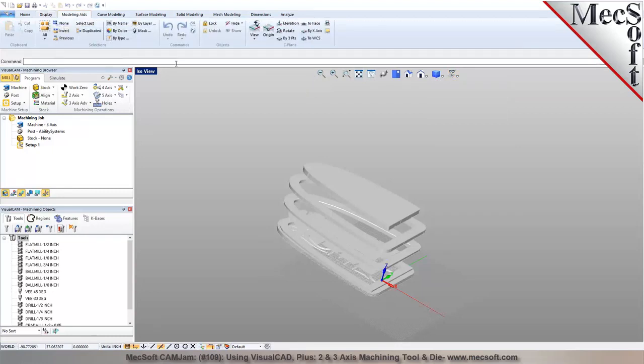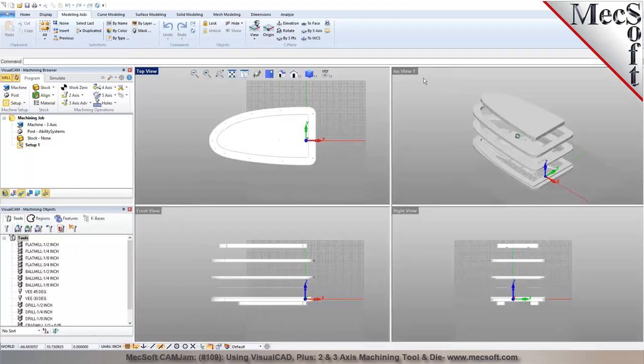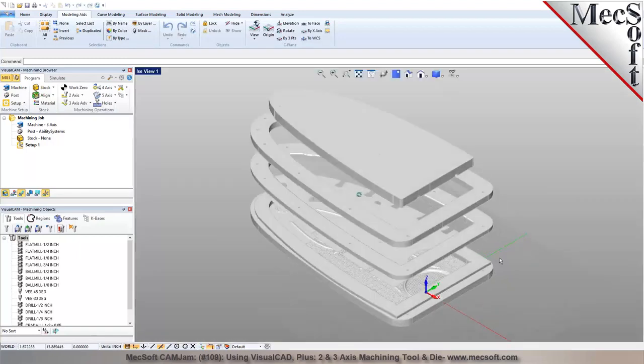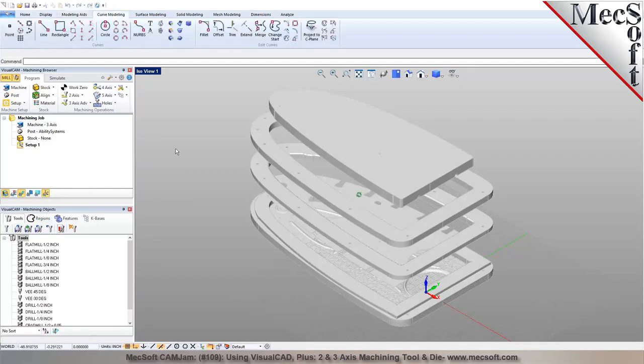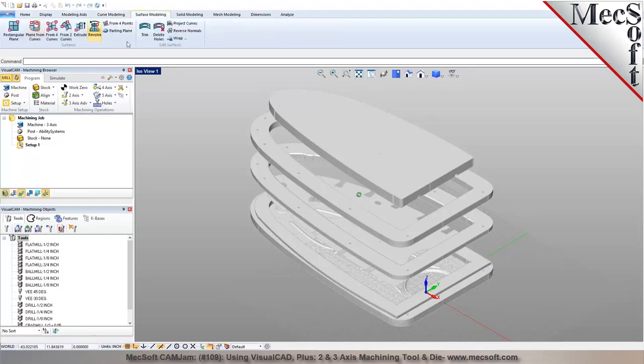And of course, you have drawing tools where you can create your construction plane, which is basically similar to what you call a sketch plane in SolidWorks. We call it a C plane or construction plane, where you can orient the construction plane to a given view or any rotation to create geometries in CAD. And we have drawing tools, similar to your sketching tools. We have 2D curve modeling tools. We have some basic surfacing tools. We do not get into any filleting of surfaces or chamfering or trimming of surfaces in the CAD modeling.